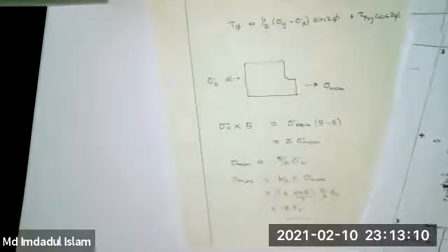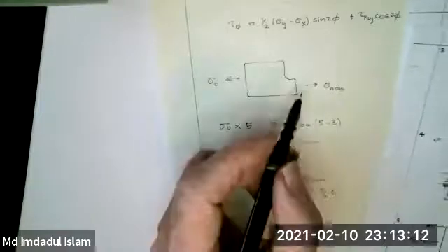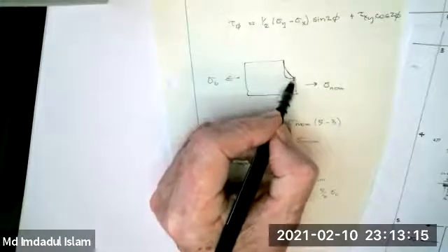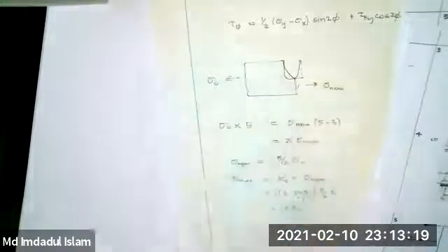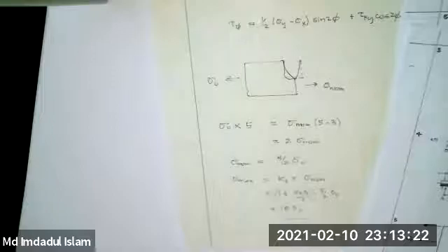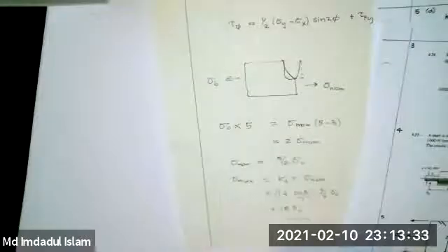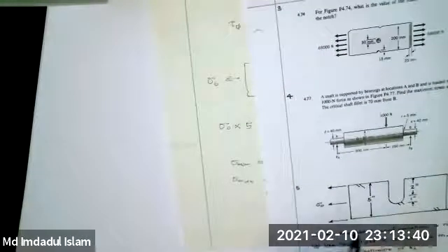And what I did was I put an ellipse inside this, like this. Okay. So you didn't use a specified value for sigma naught. That's right. You're just getting KT. Okay. All right. Cool. So you don't need the value of sigma naught. You're just getting what's the stress here relative to this? And that's the stress concentration factor.